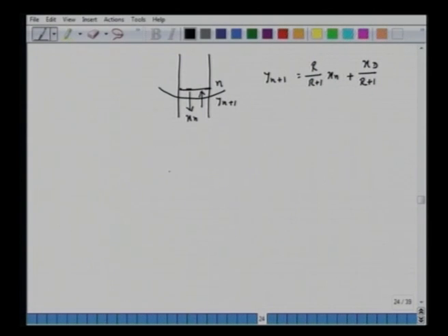Now for the bottom column, we have this mth plate, and we took an envelope like this. The stream which arrives here is ym plus 1, and the stream arriving here is xm. This flow rate here is L bar, this flow rate here is G bar, and this liquid L bar is the bottom product W, and the vapor, which is nothing but pure steam, is G bar.